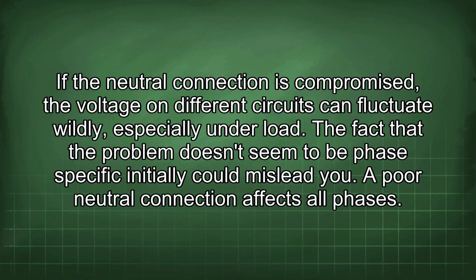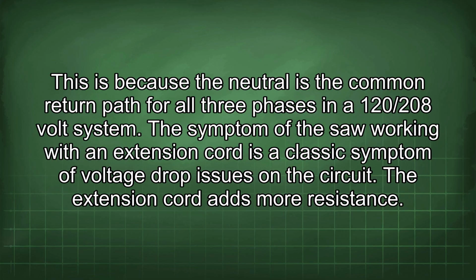The fact that the problem doesn't seem to be phase-specific initially could mislead you. A poor neutral connection affects all phases. This is because the neutral is the common return path for all three phases in a 120/208 volt system.